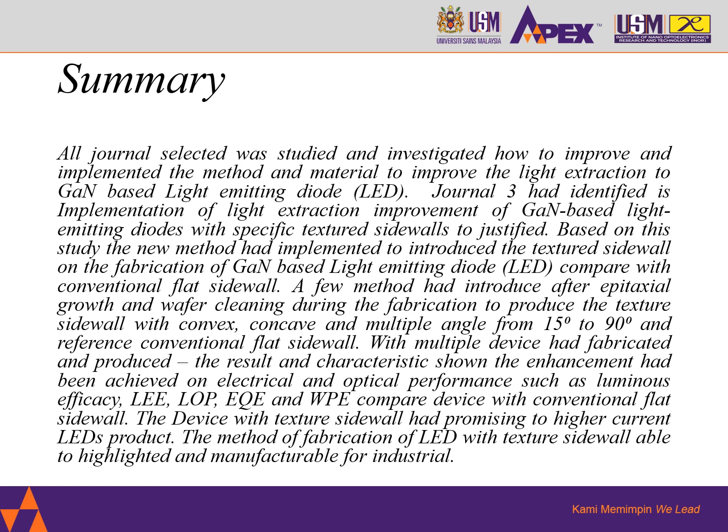Based on the multiple devices fabricated, the results and characteristics show achievement in optical and electrical performance such as lumen efficiency, LEE, LPO, EQE, and WPE compared with the conventional flat sidewall. The device with the textured sidewall is also very promising for current LED. The method and fabrication of the LED sidewall can also be highlighted and is manageable for industry in the future.